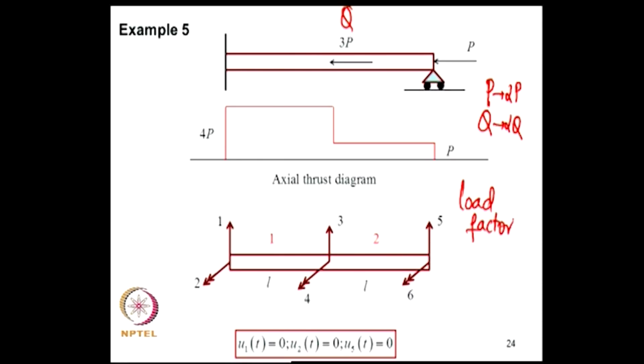So, in problems of elastic stability analysis, we aim to find the load factor. By that, we mean that for a given structural configuration carrying a certain spatially distributed load, keeping the loading pattern the same, I will increase the entire loading pattern by a constant amount. That is alpha.